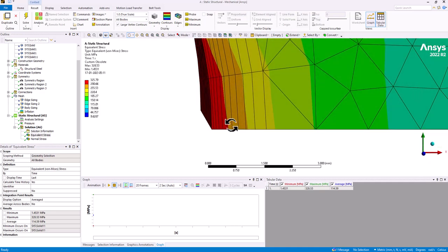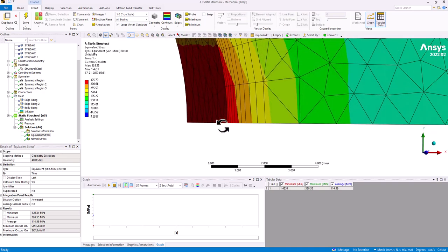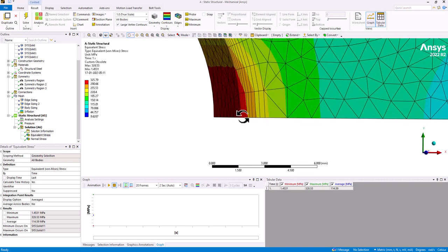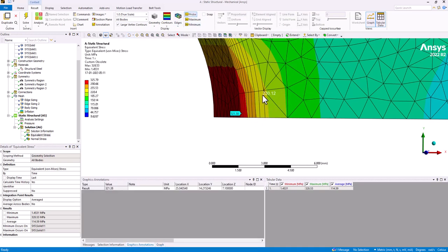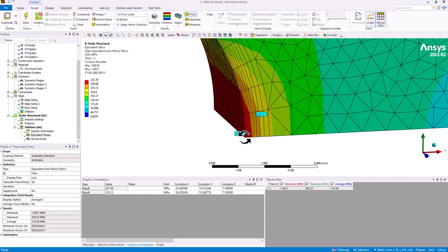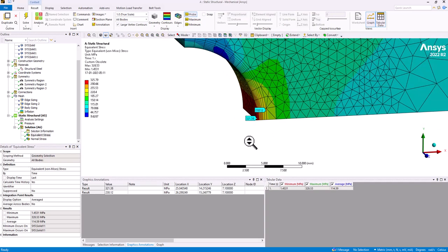But now, if we look at this result, the gradients are varying smoothly from one position to another. If you look, 300 and 231. Previously at this location the values were around 160. So the gradients are getting captured more accurately once we refine the mesh.